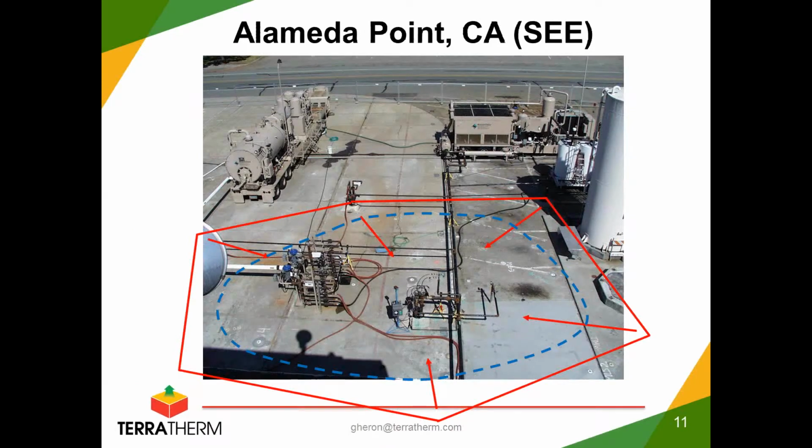Here's the first example that I was involved in at Alameda Point. The red hexagon in each of those little corners was an injection well pair, and we were injecting outside in. We were remediating an LNAPL zone with TCE in it, and the outside of it is shown by the blue punctuated line there. One extraction well in the middle and 6 injection well clusters around the outside.